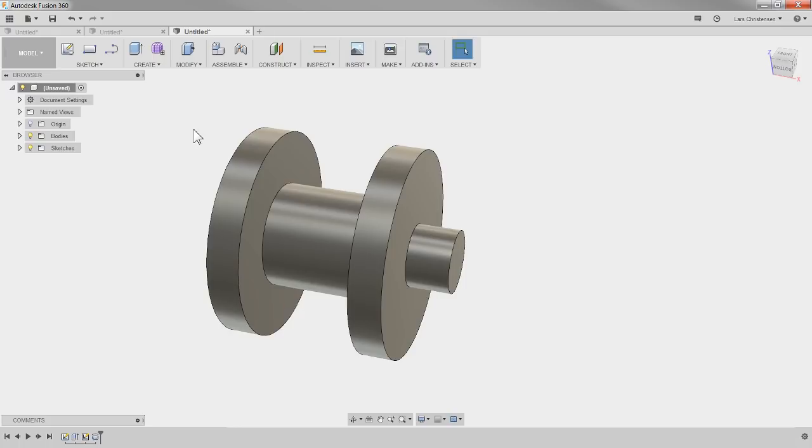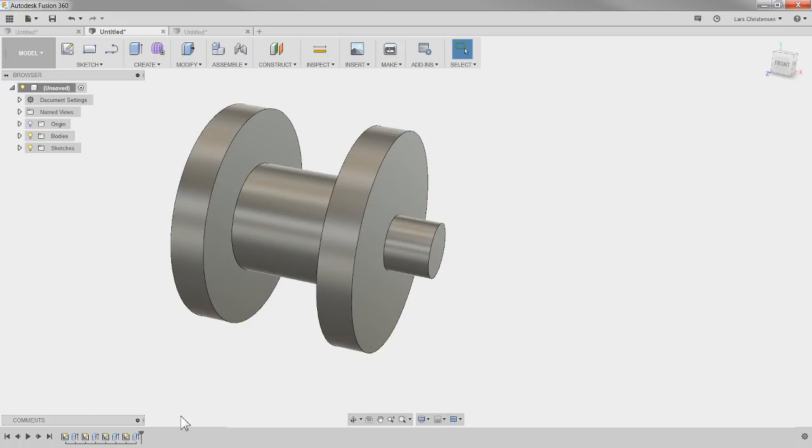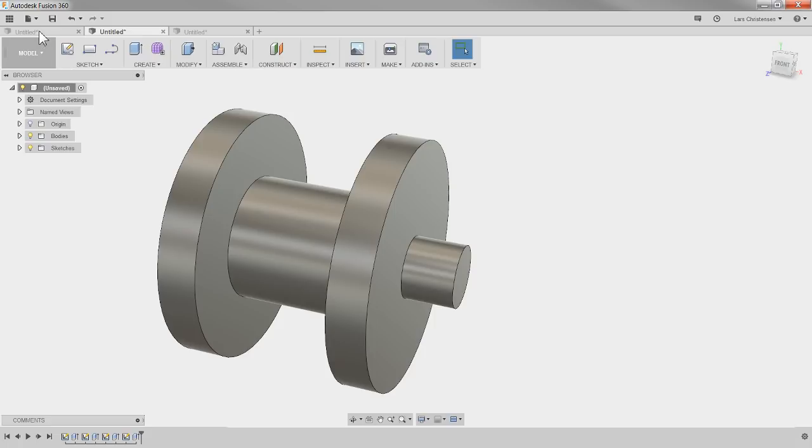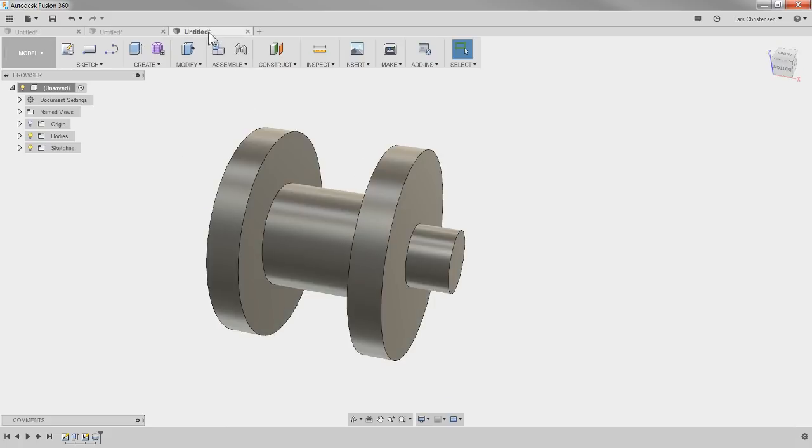So when people ask you, what is the design intent? Well, then try to think about where you're gonna end up. So I would say that if you have somebody else gonna work with your model, the layer cake might be the easiest way to break it down, though you're ending up with more features like that. I hope that was a good way to show that you can model the same part up in different fashions. And when people are talking about the design intent, you still got to end up with the right part in the end, right? It's more about how you got there.